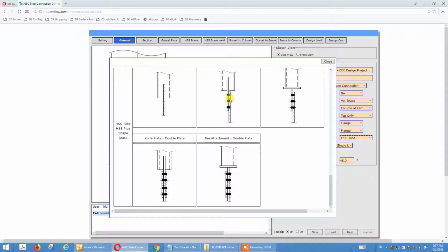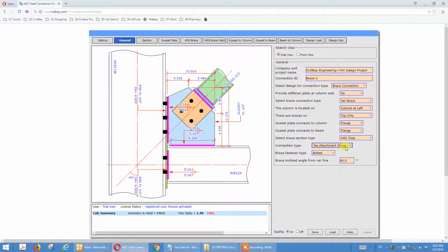Eccentric axial loads cause eccentric moment to the connecting plate. For this one, there's no eccentricity. Okay, we offer a double lap plate, and that will increase the shear critical capacity because it's a double shear plate. Increase the capacity by double. Okay, that's gusset plate, double plate. Okay, close it. I go to gusset plate, double lap plate.